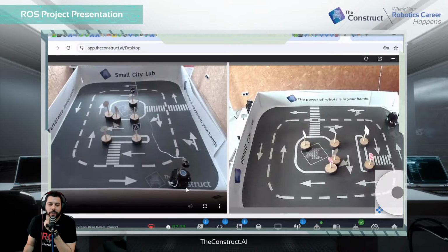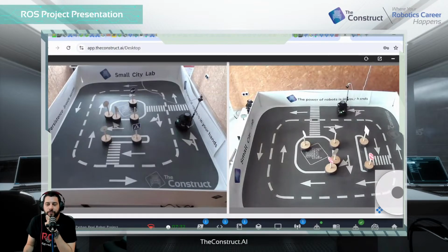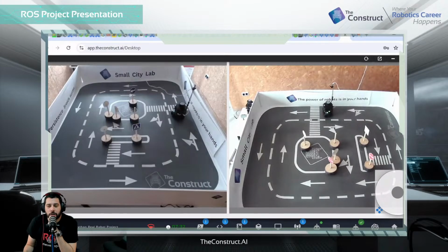Also, to reduce the wavy movement of the robot, I implemented a little bit of correction: the robot steers more if it's too close to the wall or too far, and when it gets closer to the desired position, it steers less aggressively. So it helps the robot to follow the wall in a less wavy way.